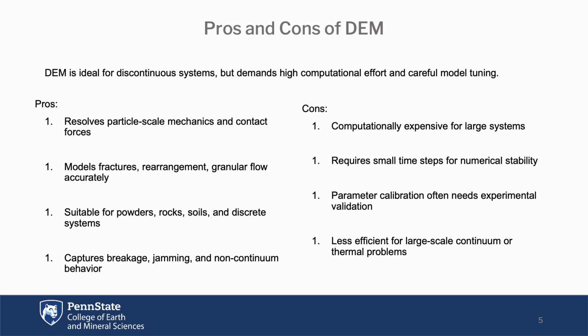Additionally, DEM excels at modeling discontinuities. While continuum models struggle with crack propagation or localized failure, DEM naturally resolves these through the mechanics of individual particle interactions. It can simulate complex phenomena like jamming, particle segregation, and structural collapse at high spatial and temporal resolution.